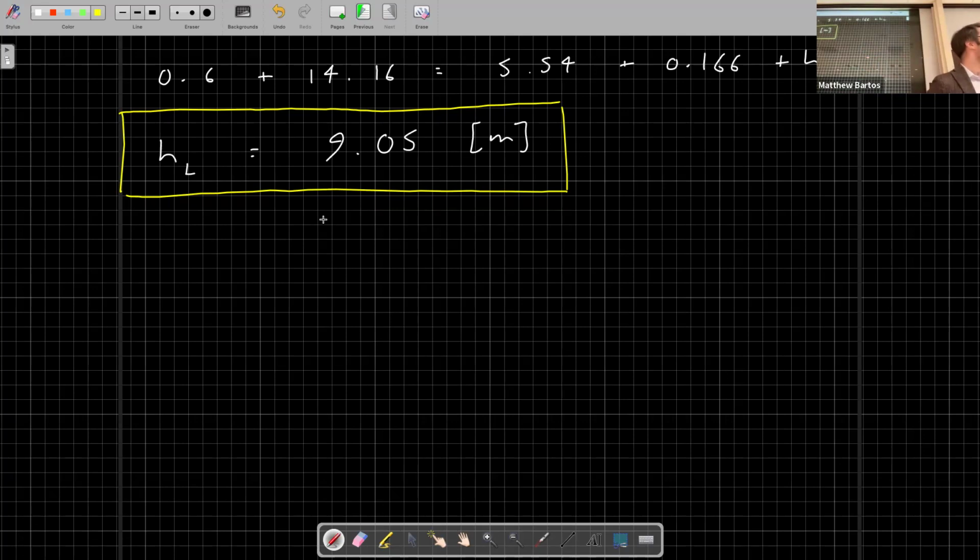Bumps, and then we put a blocker that makes it go supercritical again, and you put some more blockers. Oh, that's an interesting idea. So you could force it to transition between the critical depth several times. That's a good idea. That's interesting. There's an easier way though, kind of a more conventional way.